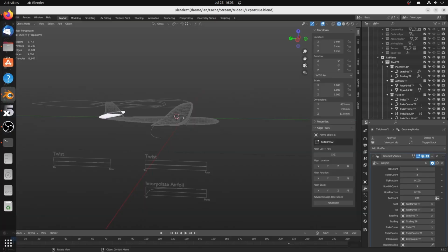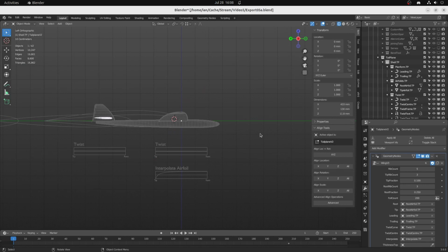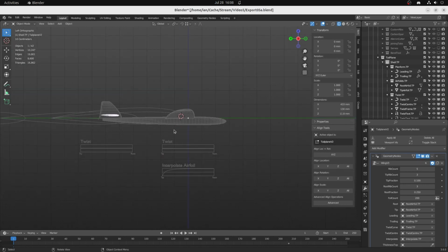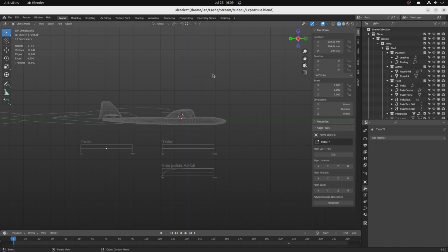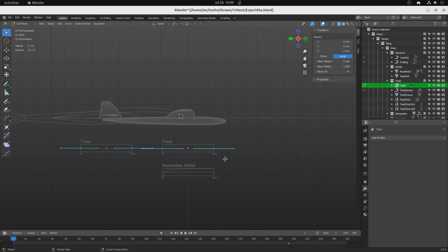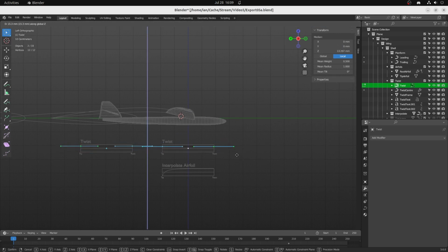is, if we look at Blender from the side, that means the plane will have to be tilted up and the fuselage won't be pointed directly into the airstream. The solution is simply to give the wing more angle of attack, and I'll do exactly the same for the tailplane so that they stay in the same angle relationship. Hopefully that means the neutral trim position will be at a 0 alpha, which means the fuselage is pointing directly into the wind, assuming we designed the fuselage to be at its most aerodynamic along the y-axis, of course. I can do that by subtracting 4 degrees of downwash on both the main and the tailplane.